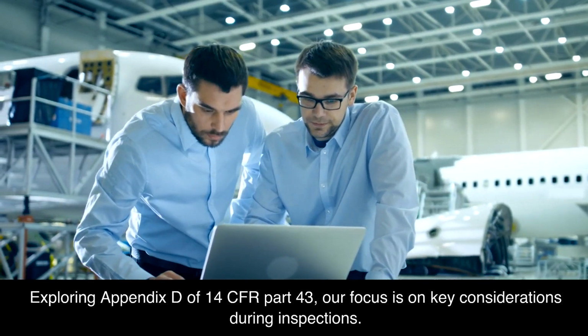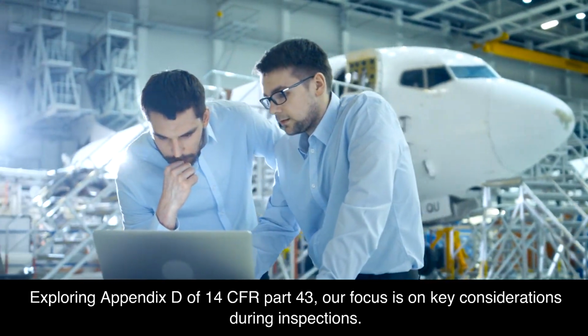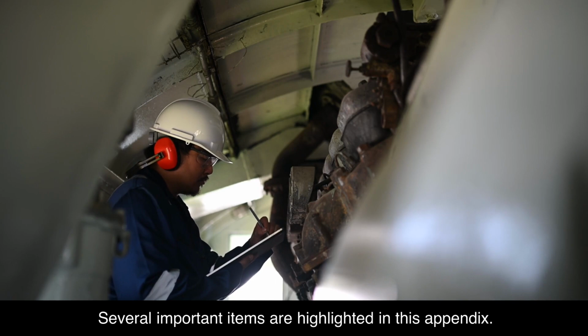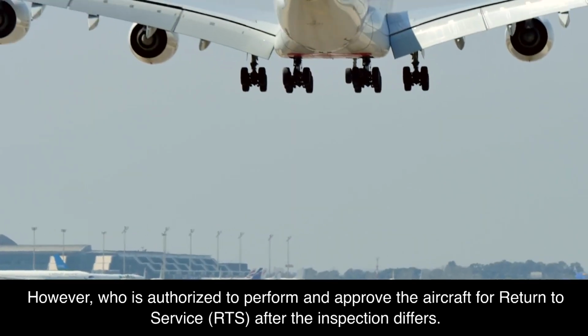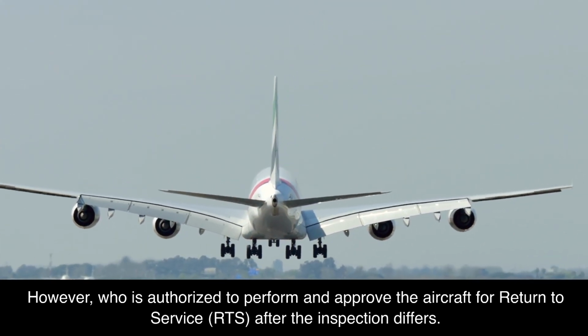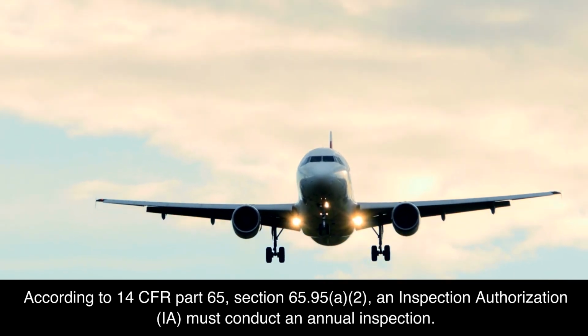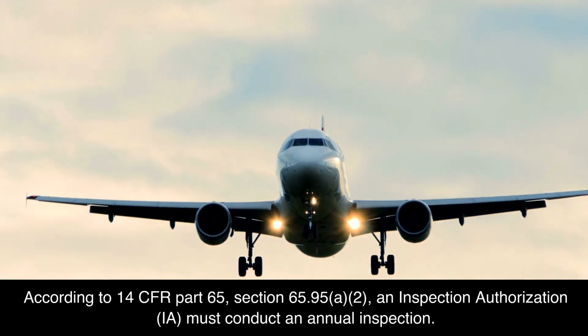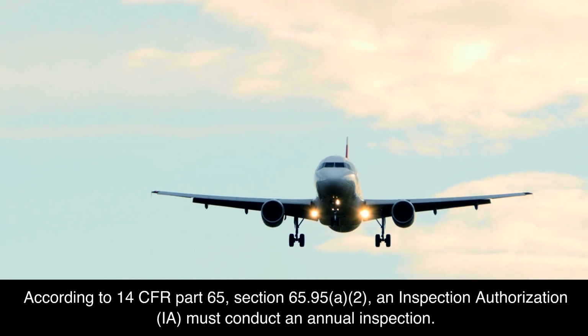Exploring Appendix D of 14 CFR Part 43, our focus is on key considerations during inspections. Several important items are highlighted in this appendix. Firstly, it's essential to note that the list of items and areas to be inspected remains identical for both annual and 100-hour inspections. However, who is authorized to perform and approve the aircraft for return to service, RTS, after the inspection differs. According to 14 CFR Part 65, Section 65.95, A.2, an inspection authorization, IA, must conduct an annual inspection.